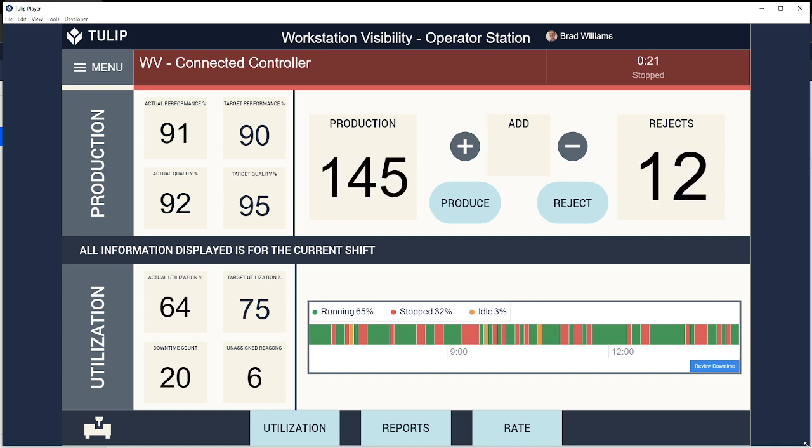And today we're using OPC UA as a means of obtaining data. So KEP Server EX is an OPC UA server, and Tulip has an OPC UA client that's reading data from tags that are being exposed. And in this case, we're assuming that this is a CNC controller, and the CNC controller might be like a FANUC controller, and Kepware has a driver for that controller, so that driver converts the information so that we can understand it.